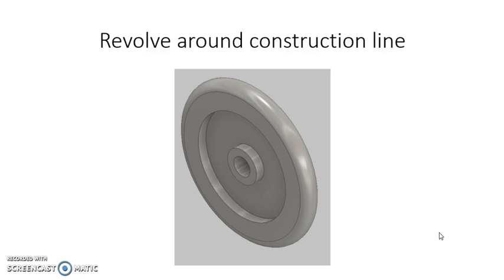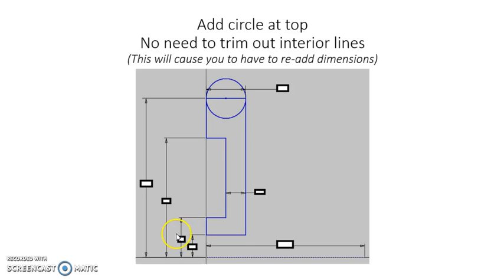We're close to the correct shape. You'll notice that this is blocky in here, right? These are 90-degree angles at these edges. That's absolutely fine. In order to get the rounded edge on the outside of the wheel, you're probably going to have to go back and select both this profile down here and then select a second time for the circle on top to make sure that it revolves as well.